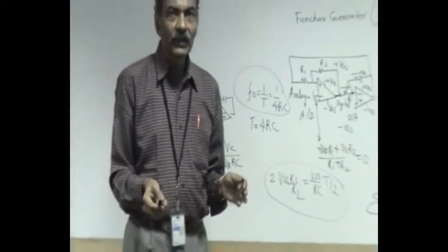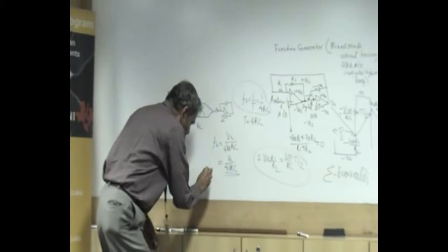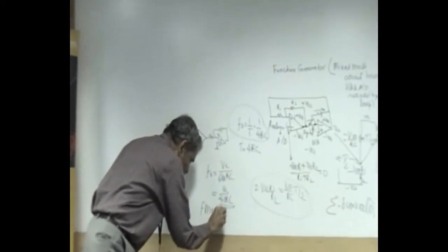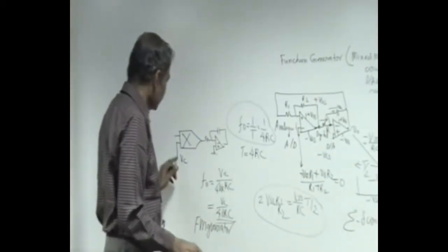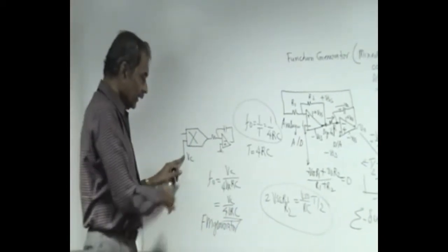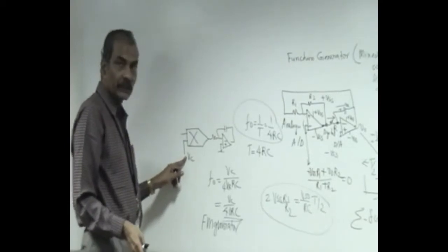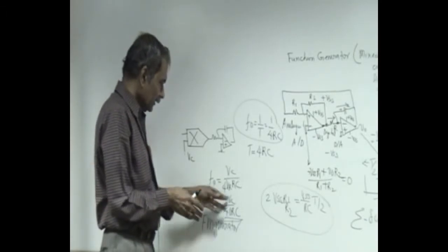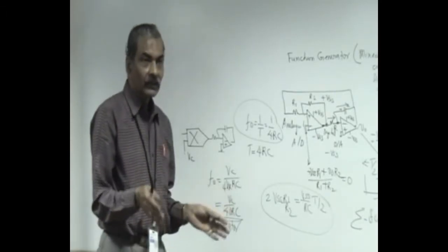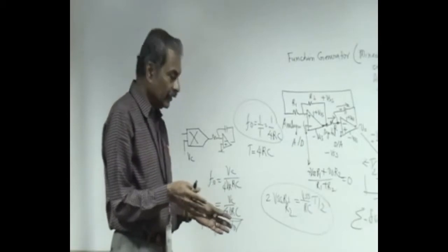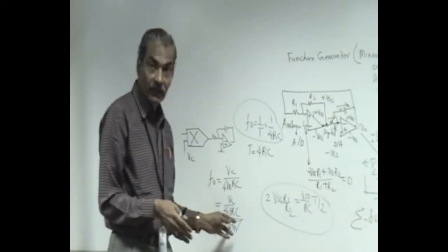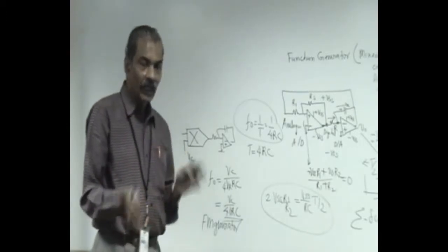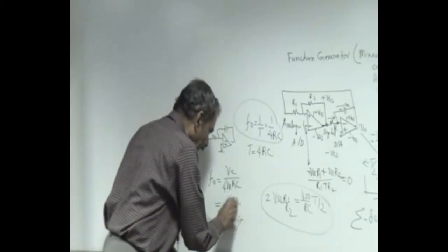So it becomes a voltage controlled oscillator, or it can be used as an FM generator. The modulating frequency is given here. Immediately it modulates the carrier frequency by this particular thing. If VCQ is the quiescent frequency determining voltage, then FQ is the carrier frequency, which is VCQ by 40 RC, and then the varying sine wave of omega m is applied over that.